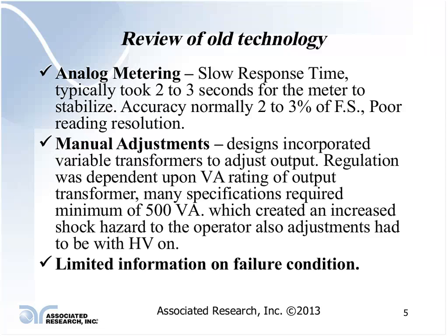And the reason for that was to make sure that the voltage did not sag during the testing process, that the Hipot had the capacity to supply the voltage and not waver under varying load conditions. So they specified a high current capacity to be able to perform the test.